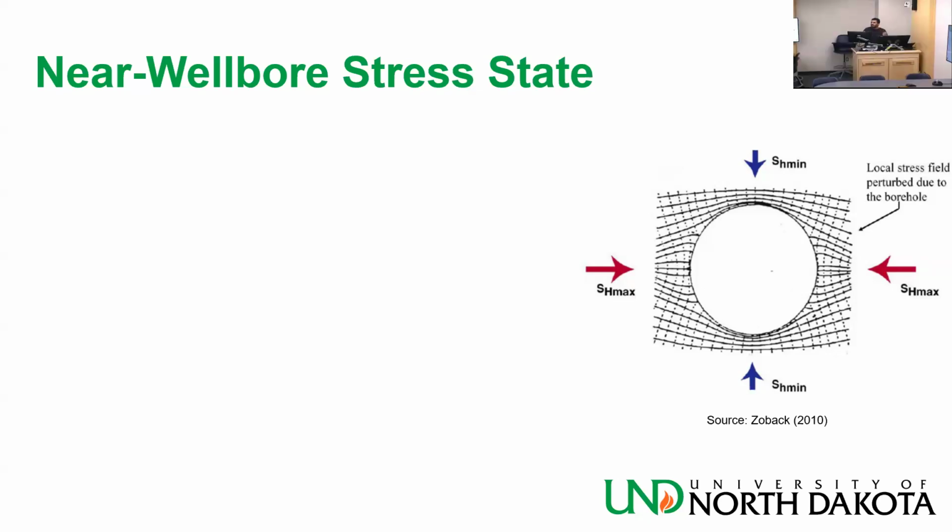Now, when you drill a wellbore, which is what you learn about in this class, you are removing volumes of rock and replacing that with fluid. This disturbs the stress field around it. So if you go near that wellbore, the stress that you see is no longer SV, SH max, SH min. It's a different stress state, which is related to SV, SH max and SH min, but also related to the pressure inside the wellbore, what we call the wellbore pressure, which is basically the weight of the mud that you are learning about in this class.